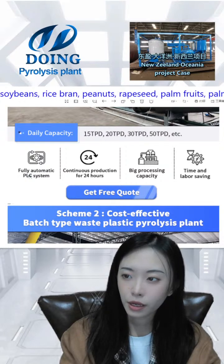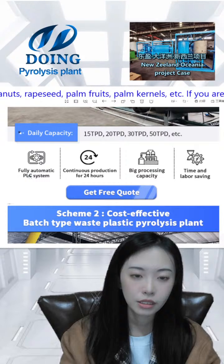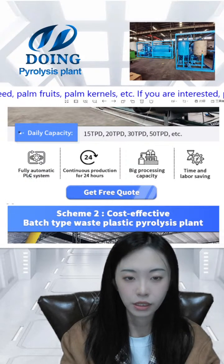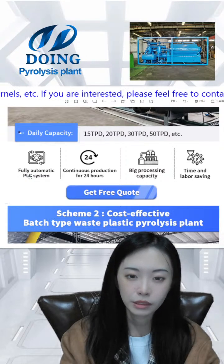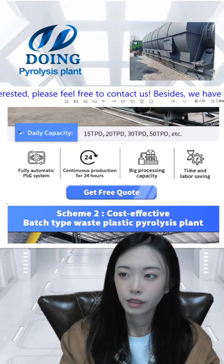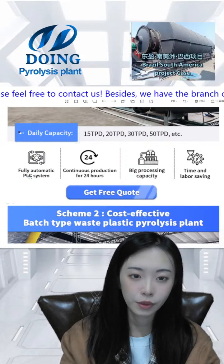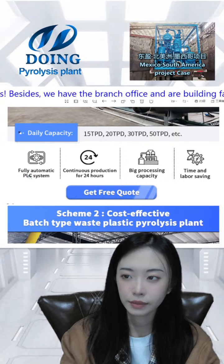And the second one is continuous production for 24 hours. This can work continuously without stopping. You don't need to cool down the reactor to discharge the carbon black. That situation only applies to the batch type pyrolysis plant. For the fully continuous one, we can work for 45 to 60 days.